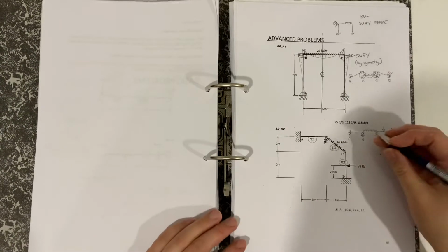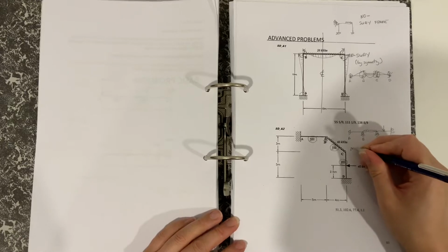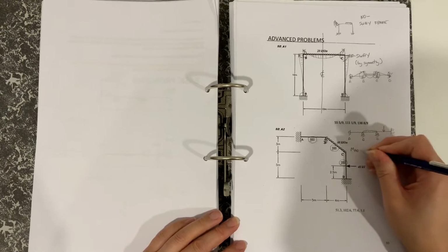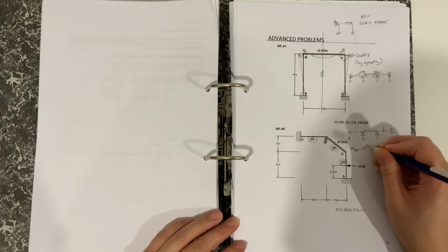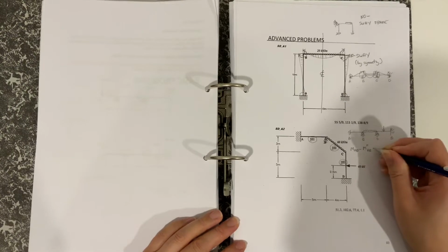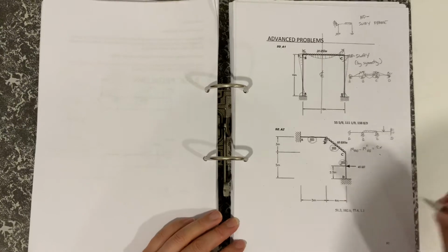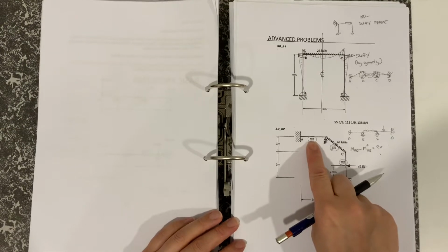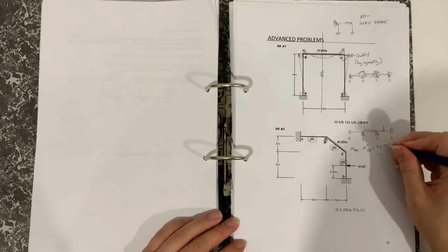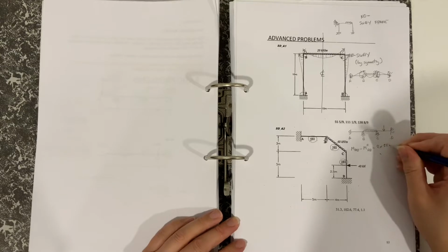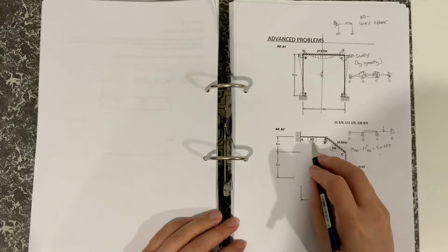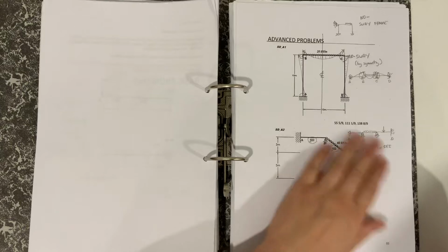So if we look at the first equation, it would be MAB minus M fixed AB, and that's going to be equal to 2 times bending stiffness. So in this case here, the bending stiffness is 5 EI. Remember, the EIs will all cancel out anyway. So if you really wanted to, you could just substitute a different value for the EIs.